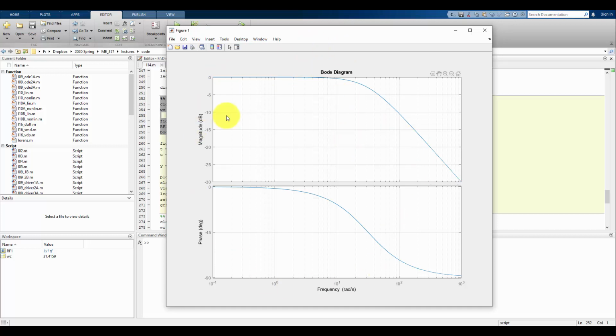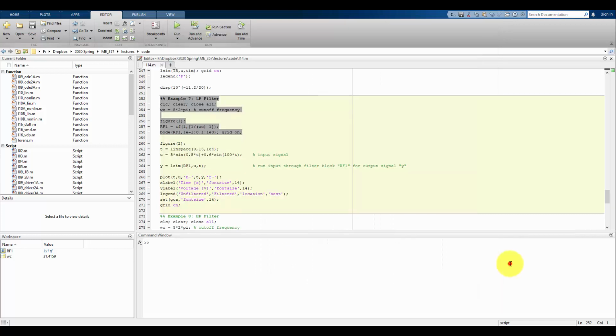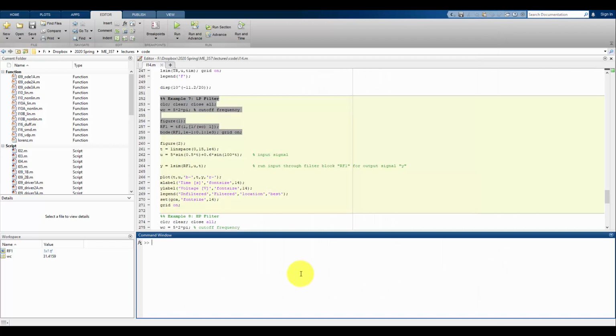But first we can look at a couple things about this Bode diagram, again specifically talking about filters. So one, we have the cutoff frequency. The cutoff frequency is really defined as the point where our magnitude is going to be equal to root 2 over 2. That's in the linear form. So we can translate that into decibels. So I'll do that here. So 20 times log 10 of the square root of 2 over 2. That's going to translate to about -3 decibels.